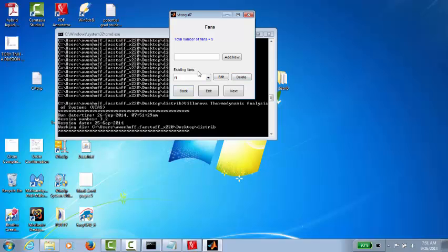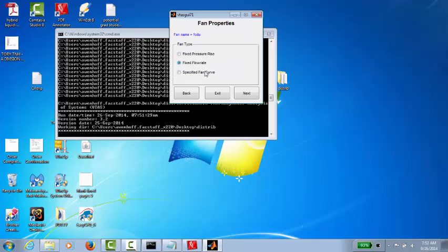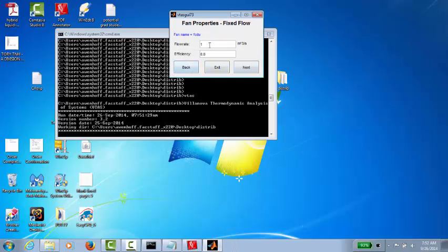Now the first difference between the standard hybrid air liquid system and a direct liquid heat exchange system is the fact that the direct liquid heat exchange system requires its own independent pump. So we're going to add in our new pump, FCDU. This will be a fixed flow rate pump, and we have to provide it with the flow rate.